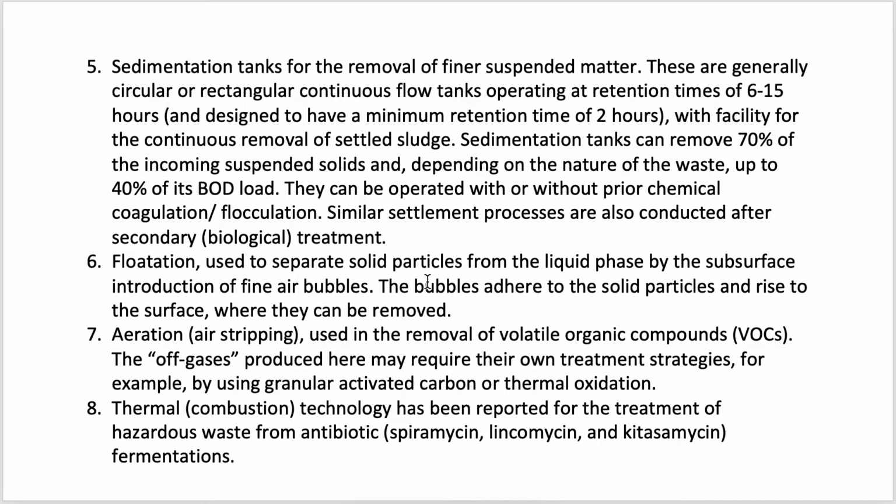Then flotation. Flotation is used to separate solid particles from the liquid phase by the introduction of fine air bubbles at the surface. These bubbles adhere to the solid particles and rise to the surface where they can be removed. Say the effluent contains solid particles; when fine air bubbles flow through the liquid, the solid particles get attached to these air bubbles and float on the surface of the liquid. Then they can be removed from the surface.